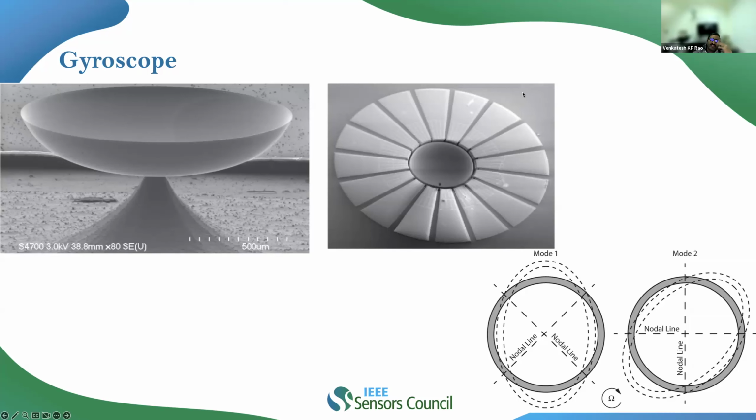In this case, since this is a completely spherical structure, we do have a perfect match between the drive and sense modes of the gyroscope. For any gyro to be in operation, the first and fundamental thing is that there should be matching, tuning the frequencies between the drive and sense directions, right? And there should be a perfect match between the drive and sense modes, and the decoupling of both modes is equally important.